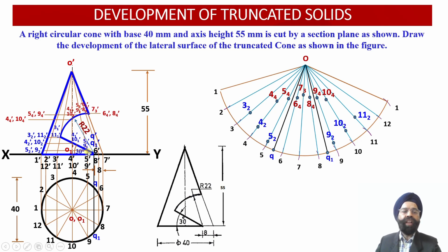So now all these points of intersection, that is 8 points of intersection alongside this straight line auxiliary inclined plane and 7 points of intersection alongside this circular sectional plane over here. So total of 15 points we have been able to plot over here. So once we join all of these 15 points into the developed surface view over here, now we will find that this portion of the cone has been cut over here.